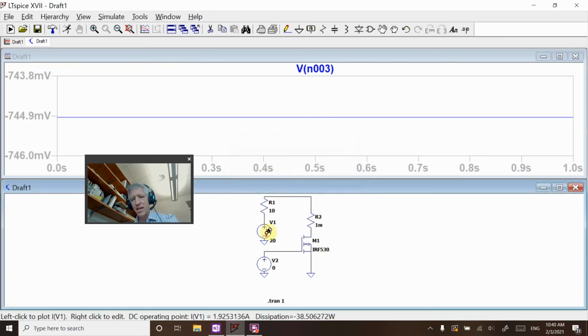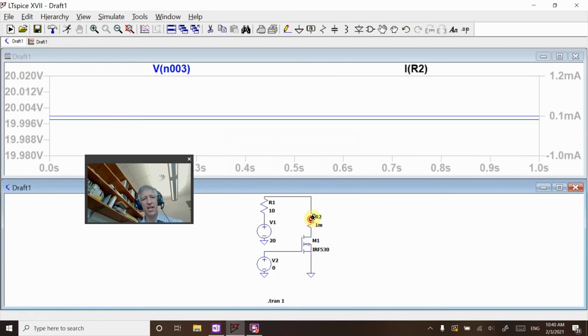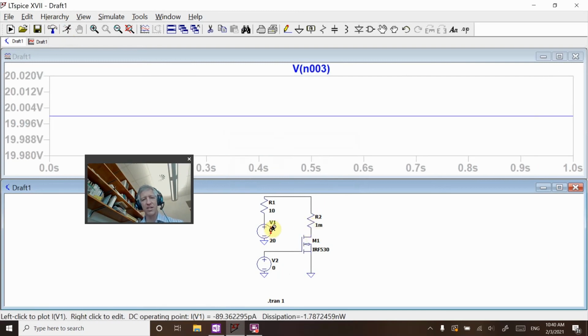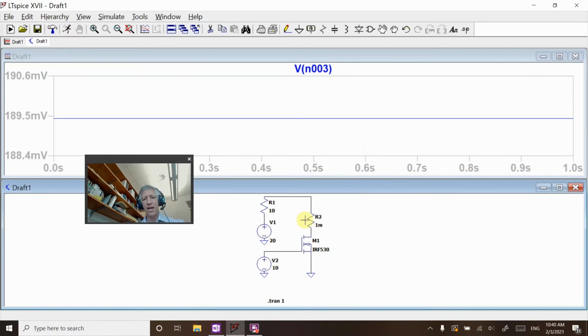So again, we start like this. If this is low and this is the voltage, I run this, you see that I get no current, and the voltage that I get is a function of this voltage. So I change this voltage, and that goes up and down. Similarly, if I turn this on, let's just say 10 volts, now I get lots of current, and the voltage here is basically 0. So now what we want to do is look at the other cases.